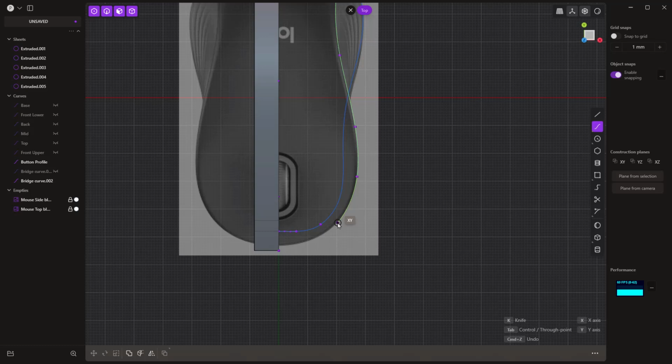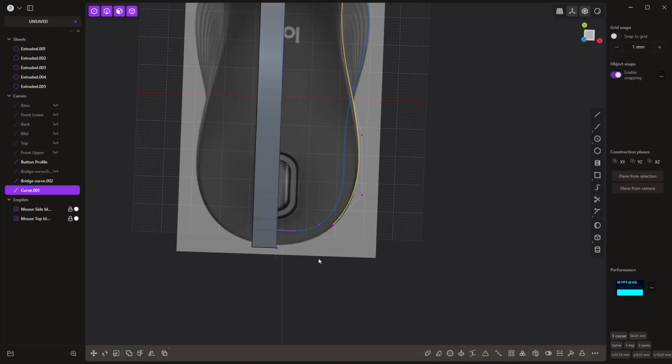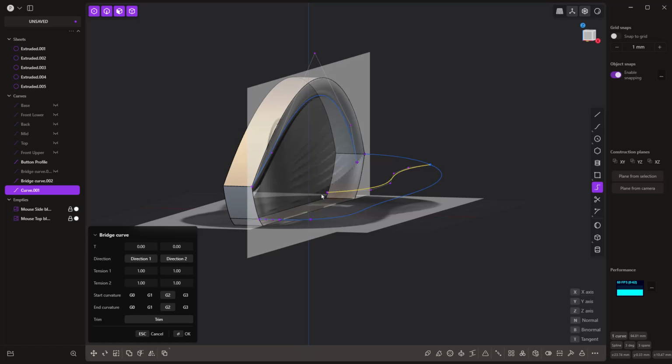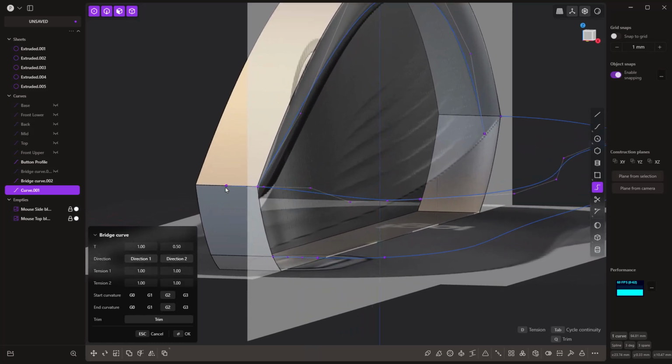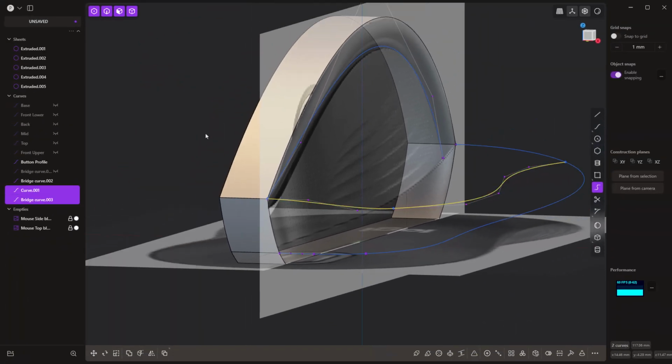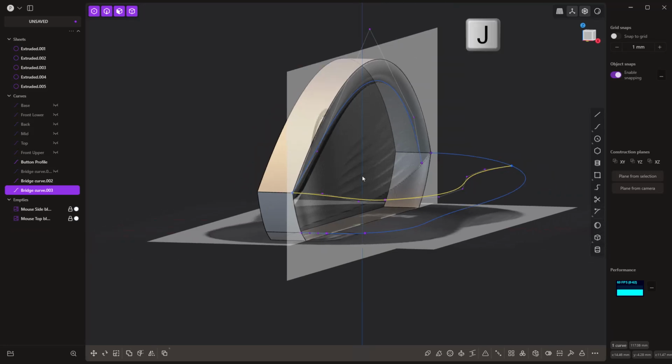And the location that I want to end up in, I'm going to just right click because I'm going to use that bridge curve again. Now, remember that this started where I selected that point. This bridge curve is a little bit lower, but I think it'll still be okay. So I'm going to come from here, hold down shift, work my way over. Now, even though I held down shift, notice that that point ended up staying in the middle because it snapped there. All we need to do is make sure that this value here is 0. G1 continuity on both, right click, and J to join.